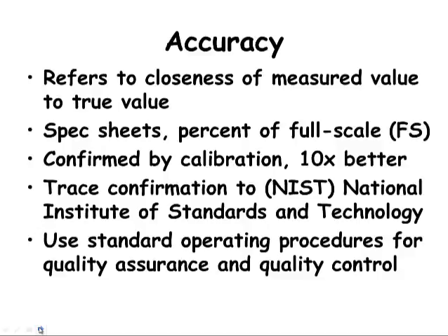Accuracy is confirmed by calibration. You'll want to calibrate a device against something that has 10 times, or an order of magnitude, better accuracy than the device being calibrated. For very important measurements, it may be necessary to trace or confirm the calibration back to the National Institute of Standards and Technology. They keep very accurate standards and can calibrate devices.